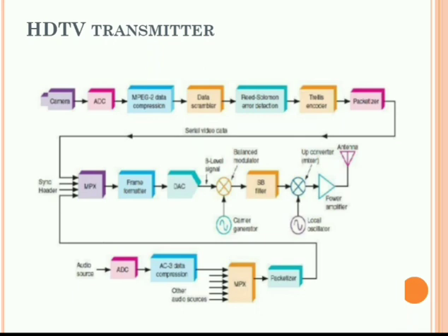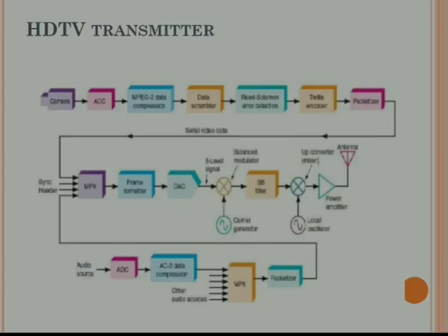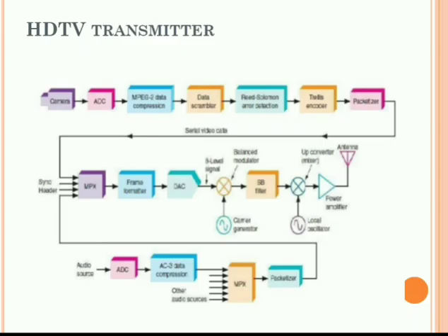What we have multiplexed before is video data, audio data, that is data streams, plus the synchronization bytes, that is 4 bytes we are using for synchronization. All these things will be present in a 188-byte packet to be used for transmission. Here, the header identifies the number of packets and their sequences as well as the video formats. The next packets are assembled into frames of data representing one frame of video.